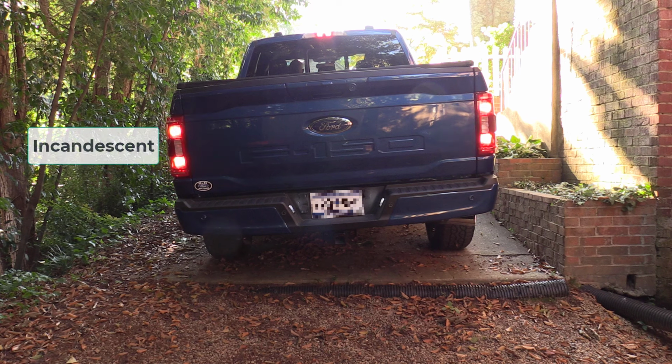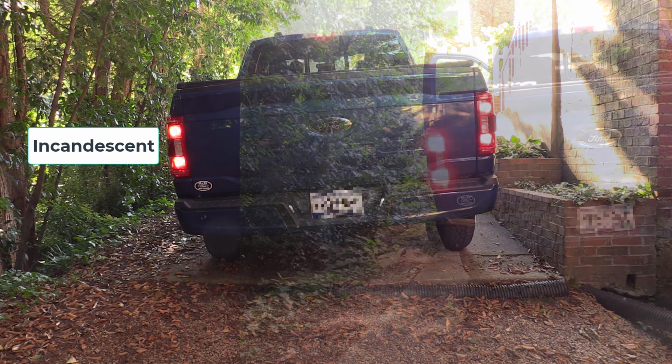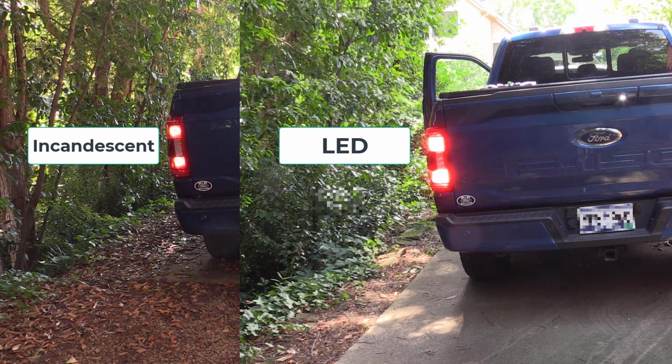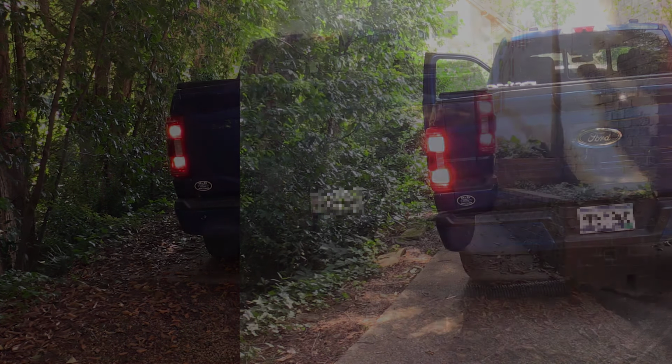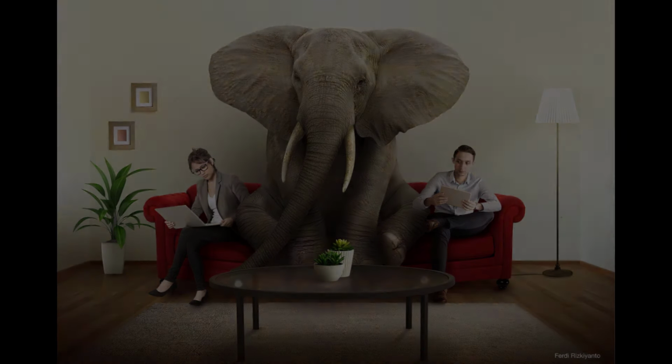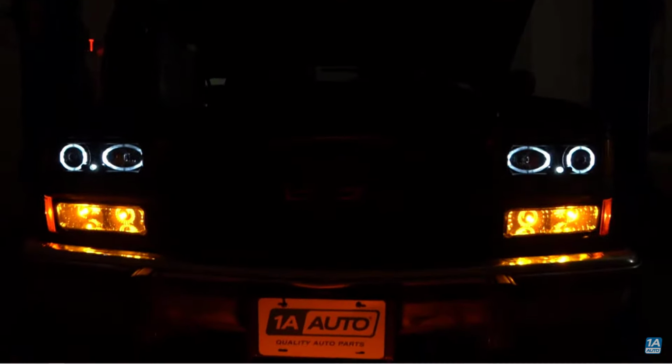Let's go. I'll bet you already know the visual benefits of using LED signal lights. They're brighter and significantly more noticeable due to their faster turn-on time. The elephant in the room when it comes to upgrading your lights to LED is called hyperflashing. All vehicles these days will make your dash indicator flash faster if it thinks that one of the turn signal bulbs is open or not drawing enough current. This is a way to notify the driver to find the defective light bulb and replace it.